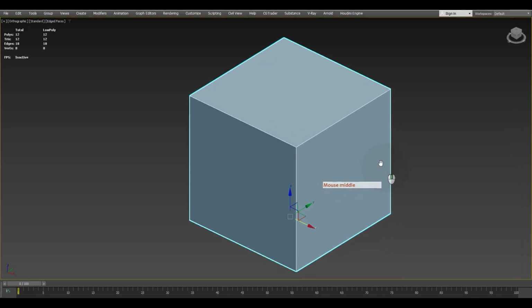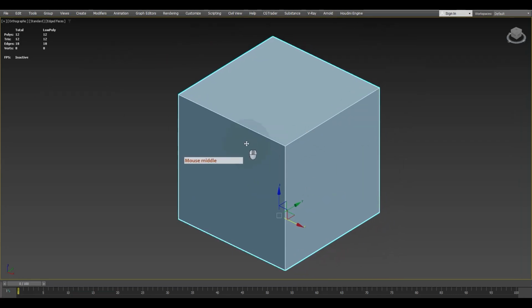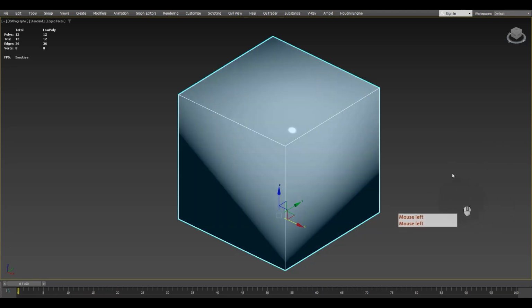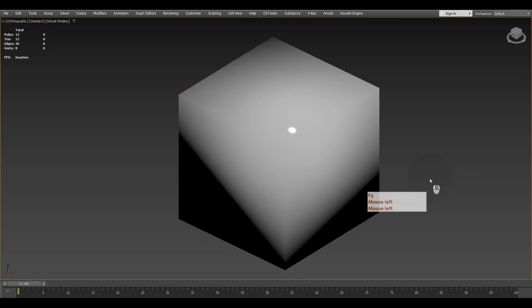So when we have a sharp edge on the surface, we need to create a UV seam cut here, okay? So the other solution for this is removing all the sharp edges, like this, okay?